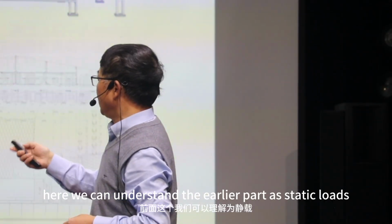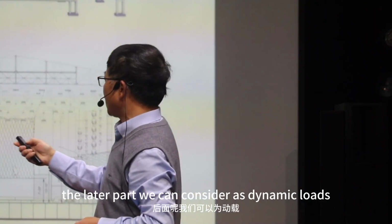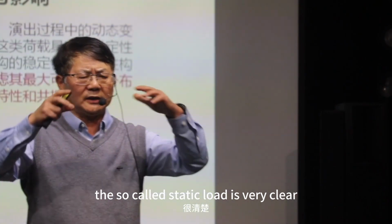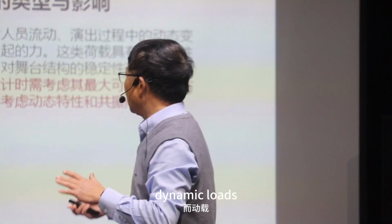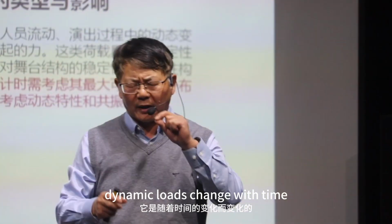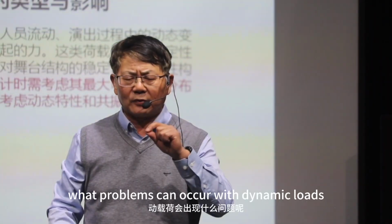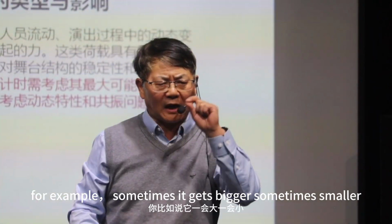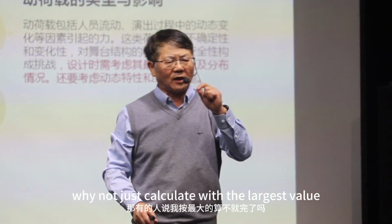Here we can understand the earlier part as static loads, and the later part as dynamic loads. The so-called static load is very clear. Once this load is applied, it generally doesn't change. Dynamic loads change with time. Dynamic loads are not as simple as imagined. What problems can occur with dynamic loads? First, they change with time. For example, sometimes they get bigger, sometimes smaller. Some people may say, why not just calculate with the largest value?